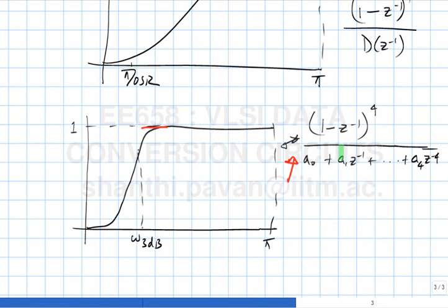While it is certainly true that this is a high pass filter transfer function, to make it a realizable NTF, or to be able to realize this transfer function shape as a noise transfer function, you must constrain A0 to be equal to 1. So what can you do to make A0 equal to 1?